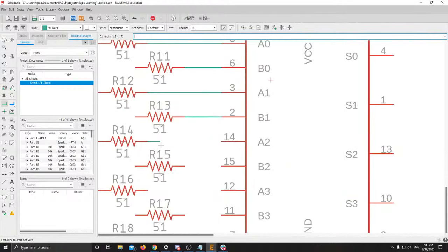One thing I did just here is I clicked in the wrong spot and did this to this, and you can just do this to this, but you'll notice you get this dot here. So generally you just want your net to go straight from one place to another. You don't want it to do any random sidetracks. I could do that, and then when I go to make the board it would be fine, but it just keeps it cleaner, and sometimes these can cause issues that you just can't really catch later down the line. So I'm just going to go ahead and undo that and restart and do it like that.